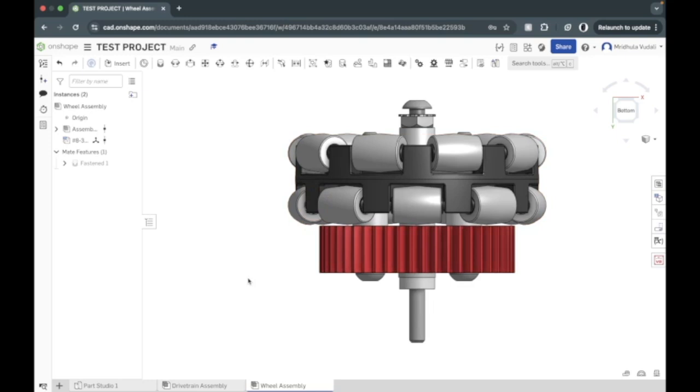I'd like to give a short side note before I show you how to use these subassemblies. As you can see here, there's a gap between the bottom face of this 2.5-inch screw and this caps nut. However, they're still fastened together using a fasten mate. This is called offsetting. You can see here that I've offset the screw from the nut by 0.062 inches in the negative Z direction. The offset allows you to lock all degrees of freedom together whilst also allowing separation between the parts.